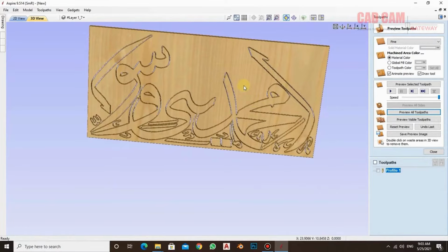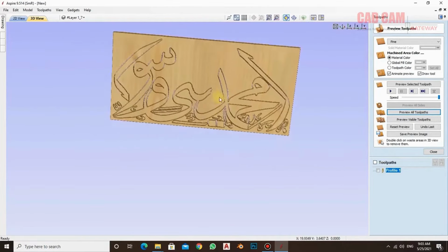All right. After this, the question arises, these joints will remain. So how do we remove them afterward? Well, that's not difficult at all. A depth of 3 millimeters or a thickness of 3 millimeters doesn't really matter. You can easily cut and remove these with any small cutter. Basically, you just lift the entire sheet, and with great care, you can gently cut and remove these small pieces from there. So it's not a big deal.